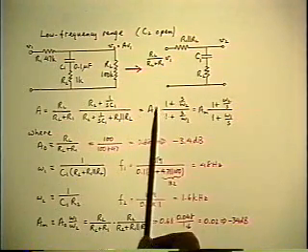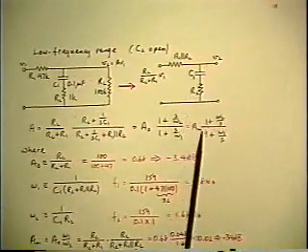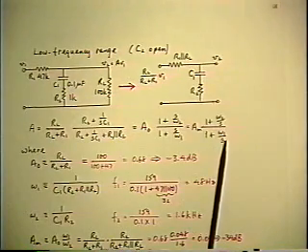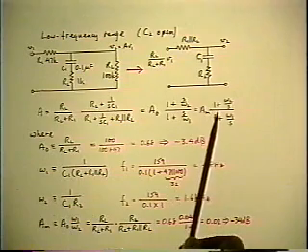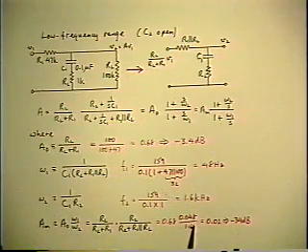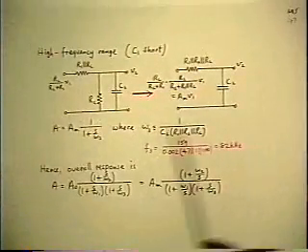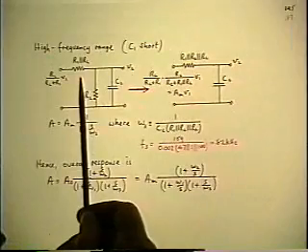So you get a zero frequency flat gain and a normal pole and zero, or you get a high frequency flat gain and an inverted pole and zero, and you can write these results down directly. There are the numerical values. The second part of the solution, the C1 is now a short. We've already made the Thevenin reduction.